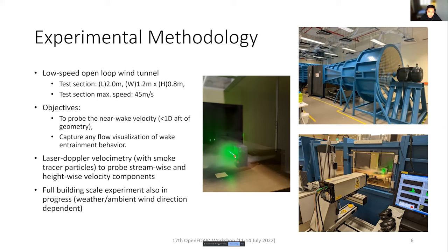The measurement technique that we have chosen is LDV, laser Doppler velocimetry. The reason why we chose this is because it's non-invasive, meaning that there isn't a physical probe inside the test section that would affect the flow field, because we are measuring something that's so close to the object itself. Anything like, for example, a pitot-static tube would most likely interfere with the results that we are